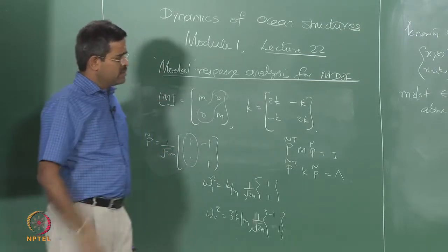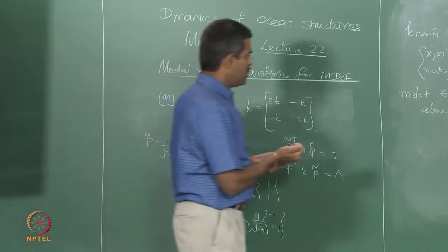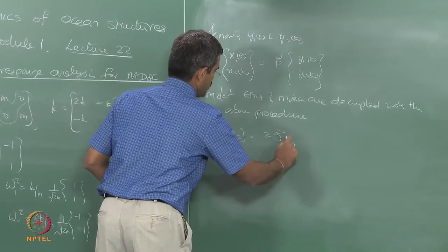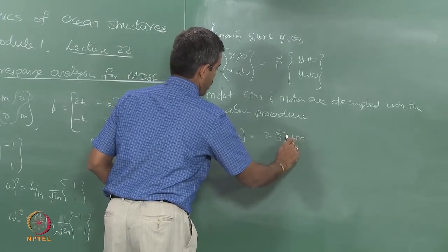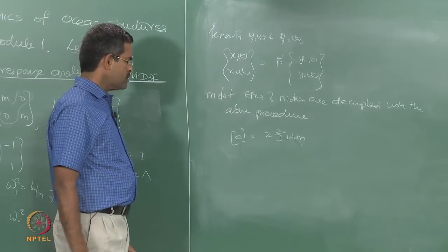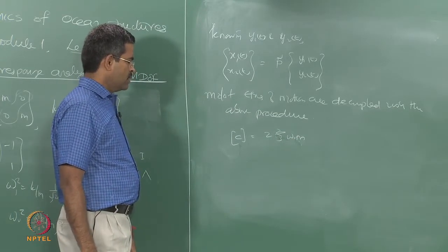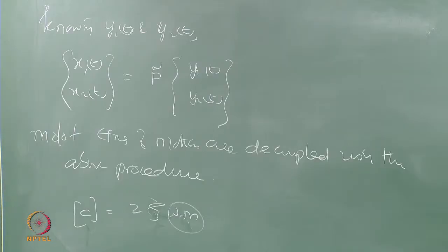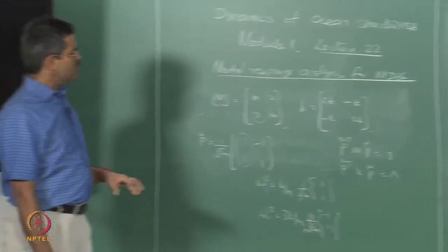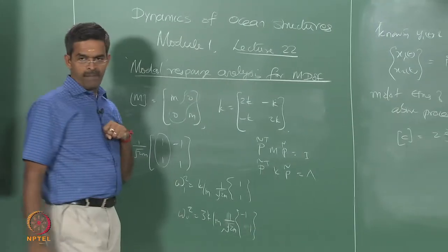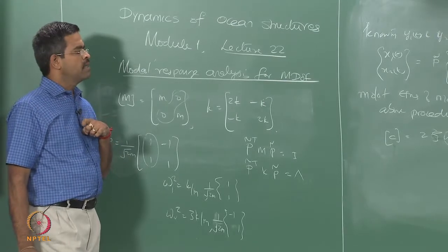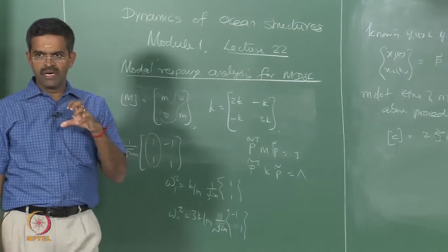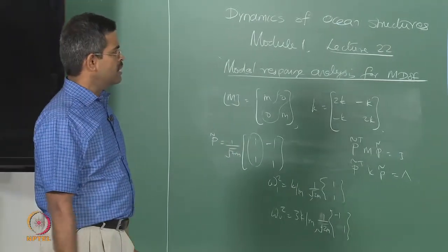Okay. And we all know that damping essentially comes from 2 zeta omega n. So, it is actually a dependent variable of k and m. So, the damping should give me a proportion of k and a proportion of m, okay, that is the idea. What is the proportion? If k is 100% or m is 100%, in what mode and how much, that is the idea. How to catch this idea is what we will discuss in the next lecture.